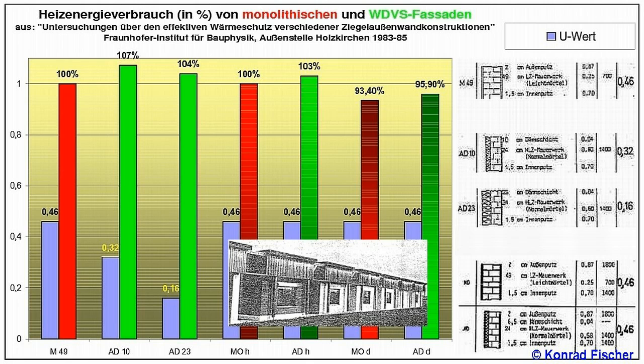Secondly, they built facades with the same R value with and without external insulation. First with white surface, then painted with dark brown color. In all cases, the insulated buildings consumed more heating energy for the same temperature level. A scandalous result, but hidden and neglected until now.